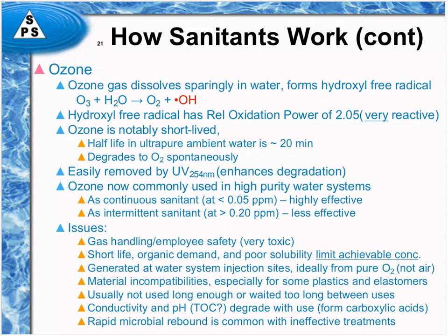Microbial rebound is very common with ozone use and is usually associated with an ineffective treatment. The problem with all of these oxidizers, and you'll see it listed, I believe, in every one of the issues, is that it's usually not used long enough or strong enough, and often you wait too long in between uses for it to be effective.